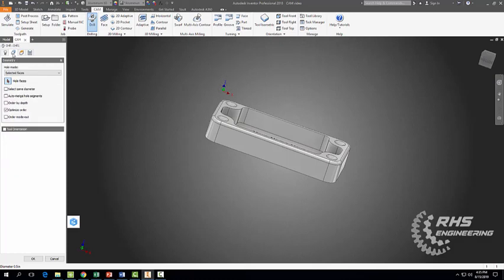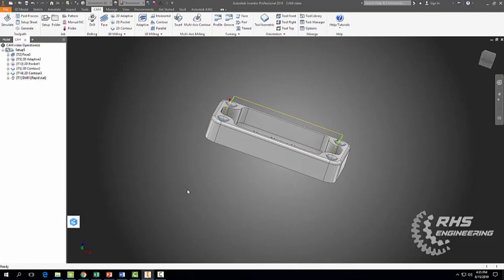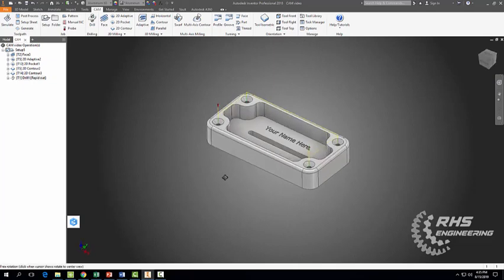And over here in geometry now, we want to select on these conical shaped cone parts. And that's pretty much it. We'll leave all the other default values in and we'll hit OK. All right. And when you're done, you should end up with a toolpath as such.